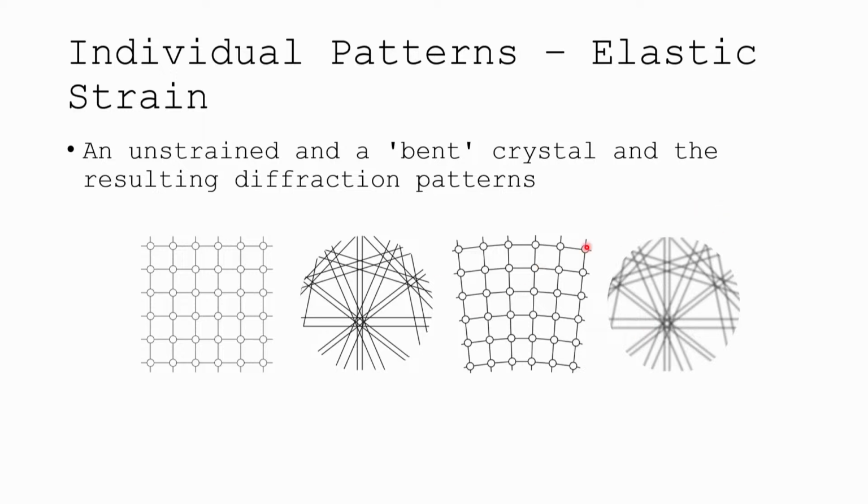Okay, if we have a bent crystal, then you have a different orientation at each point. So if you can go in and measure, you could measure orientation at each of these positions. If your diffraction volume includes all of this, it just makes your bands more fuzzy. It goes from being sharp to fuzzy. So you get these diffuse bands instead of the nice sharp bands. So you say, okay, good, we get diffuse bands. Can we come up with a measure of those? A lot of people have tried and haven't come up with any real good measure for plastic strain.